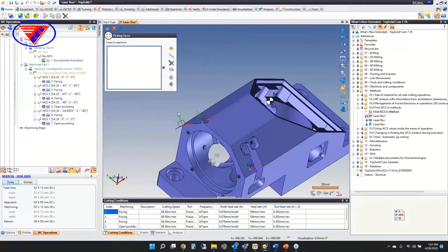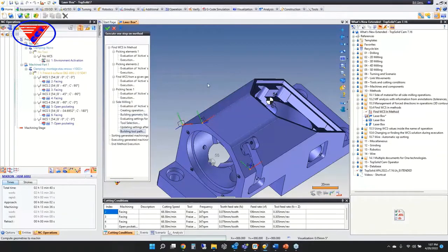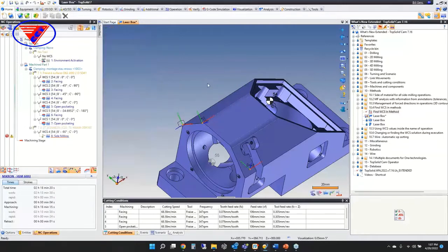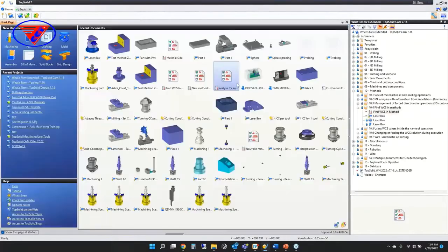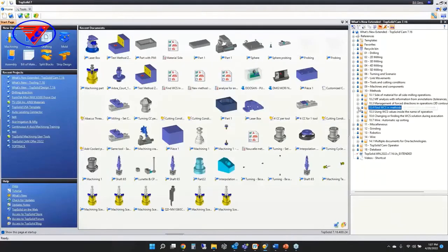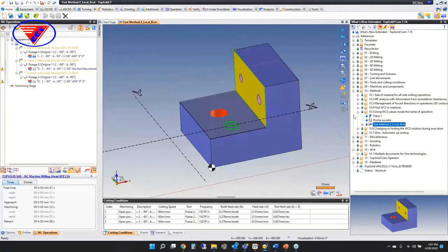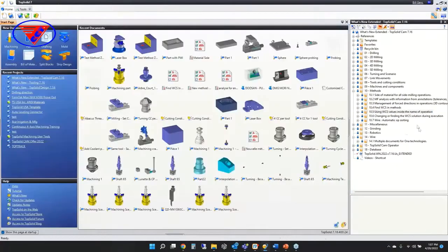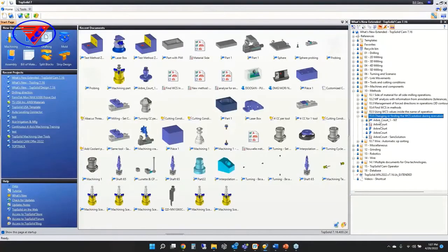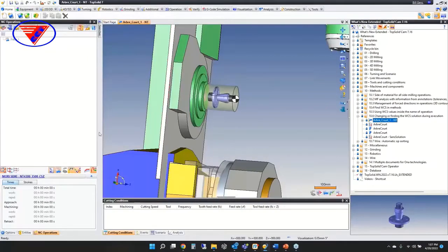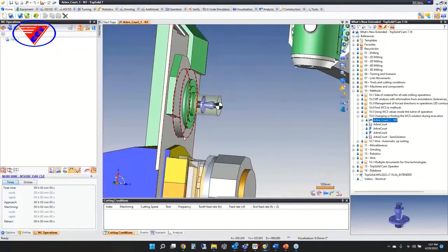And then you can select the face to machine. Maybe I want that face. Okay, and at the end of the day, what you're going to wind up with is your toolpath following that referenced face and following that origin. Next, I don't care about this one because it's basically the same as the other. This next one is interesting, especially for people doing turning on B-axes.